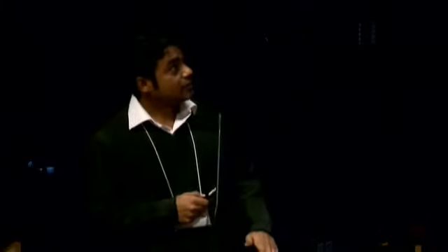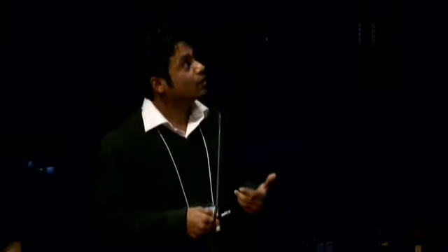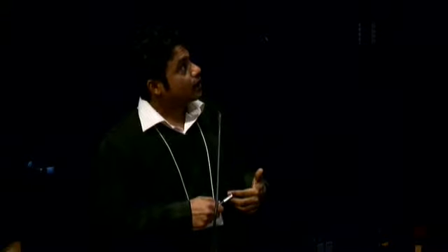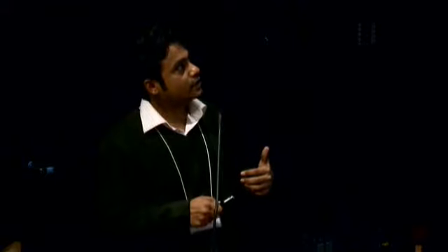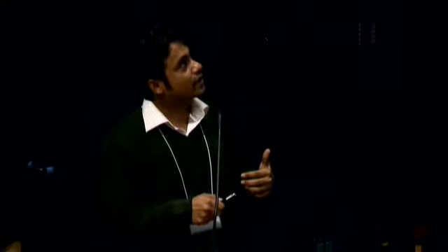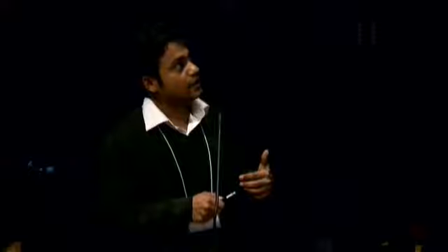This result compares the numerical versus the analytical expression that we have simplified to implement in a SPICE model. The left figure shows that if we use the same effective mass, there is a large error, around 17%, in the analytical version of the current; the red curve is the numerical and the blue curve is the analytical version.